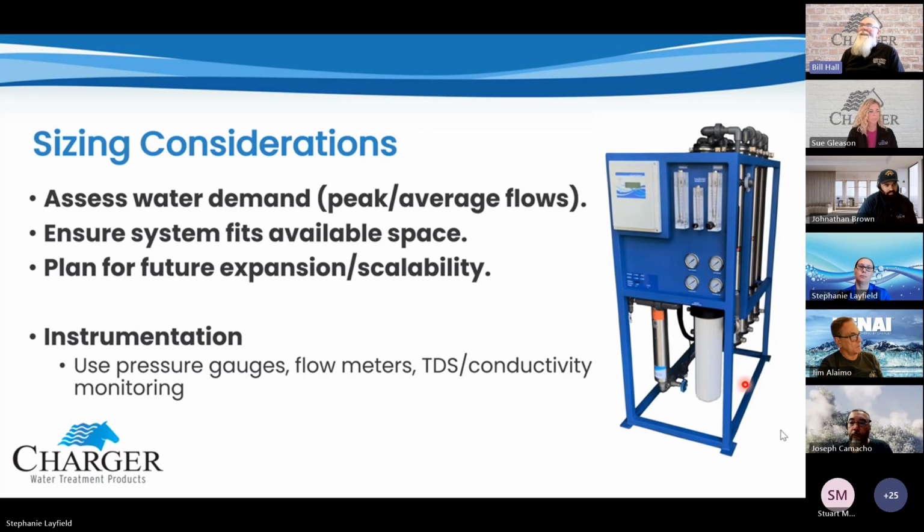Some people think that, gee, these membranes crapped out quicker than I thought they should. Apparently, I've got a bad membrane and I want warranty on it. Just speaking from experience, if you go back to the membrane manufacturer and say, I think this should be a warranty thing, you need to show them some data. They're going to ask right off the bat, did this thing work when you first put it in? If so, it's not a membrane problem.